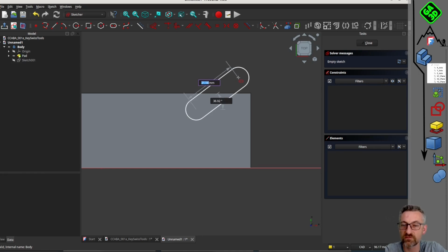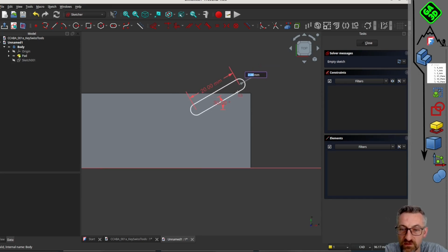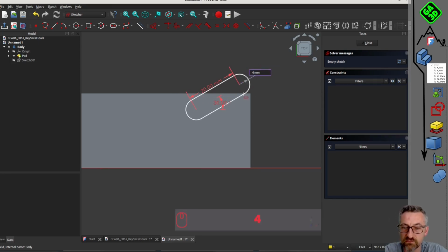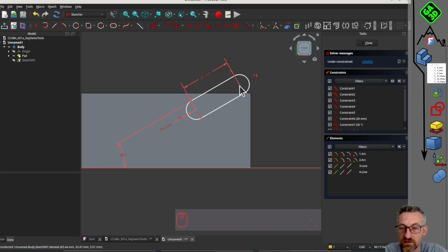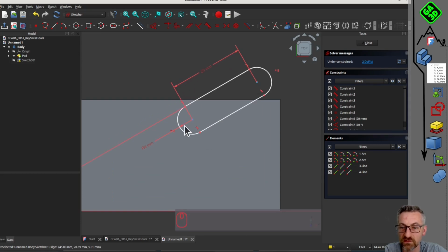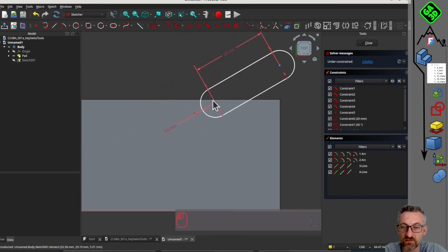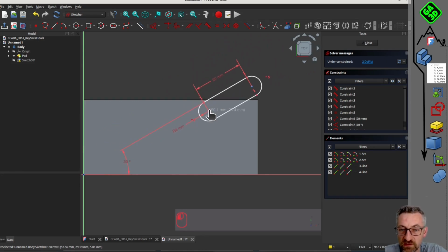So, let's go. So my sketch for the demonstration, I'll choose to fix it on this face. I click on this face, I click again on Create a Sketch, and then we'll do this small notch to serve as a bottle opener in my multifunction tool. So for now I set it like this. Length is 20. I want it to be at 30 degrees. There you go, it positions itself. And then for the radius I set 4 millimeters, and there you go, we're about there.